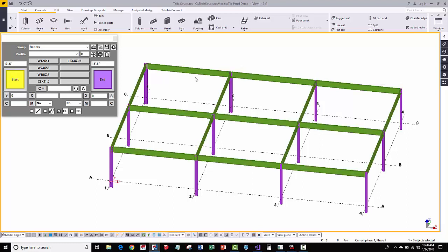Now that we've got our main girder beams in here, let's do some infill beams. So I'm going to set the number of beams to go inside of this bay to be 2. Then I'm just going to click on the profile that I want to enter in here, and now instead of picking points, I'm prompted to pick a part. So I'm going to pick the first girder, which is the start end of the beams, and then the second to span those beams across that bay. So again, we can copy these, or if we just activate the command, let's say that we do a different beam size here. We'll pick on the girder, and then the second girder, and then those beams are added.